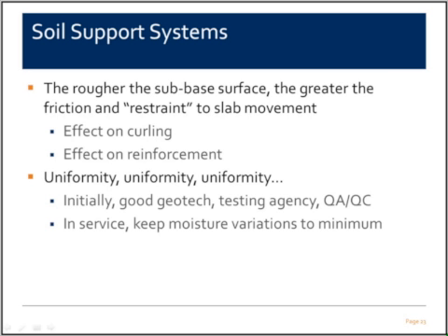The most important thing for slab on grades, in my view, is the uniformity of the soil support system. Initially, you want to have a good geotech testing agency and QA/QC procedures to keep everything uniform. And in service, you would like to have a good design so you keep the moisture out from underneath the slab by deflecting it away at the building edges and putting in drainage and so on.